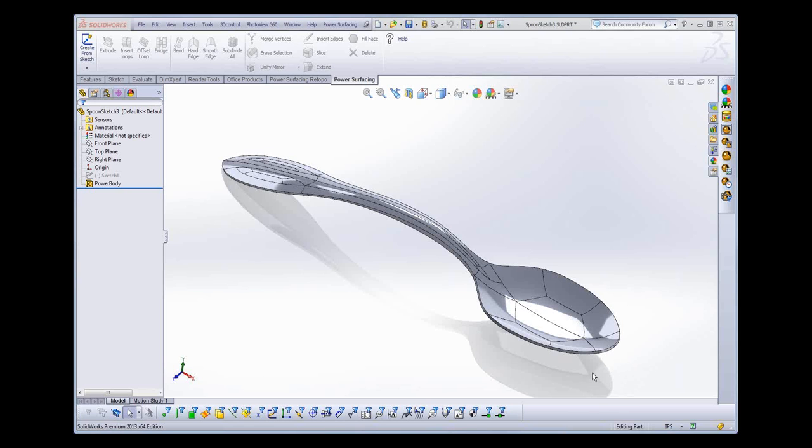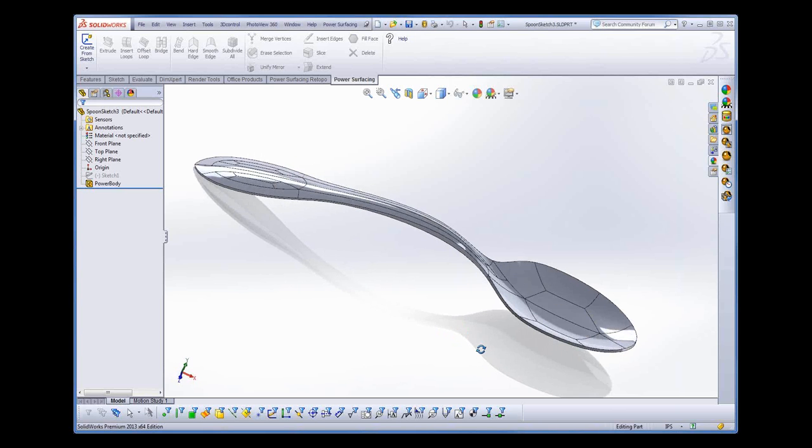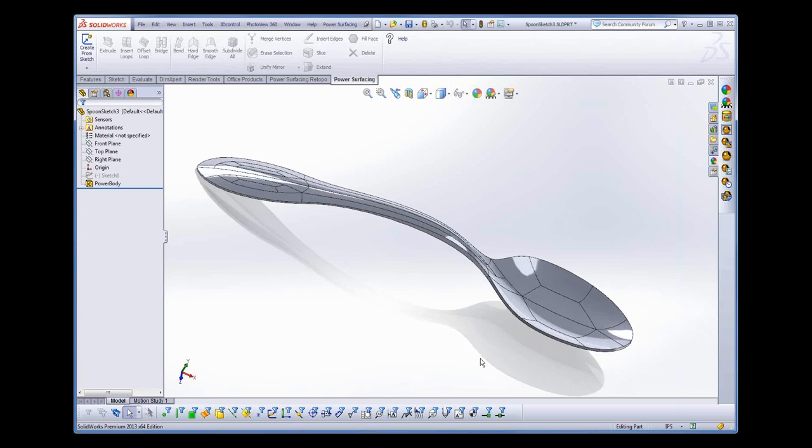One, I'm just moving the vertex, and if you think back to your splines, remember one point in the spline, the others will kind of tweak a little, or the curves in between. So that's sort of what happened there. It maintains the continuity, the curvature. It stays curvature continuous if you just pull on it. But if you crease it, you change the continuity. If you weight something, you increase the curvature around it. Whereas if you just pulled it, it still would have that same sort of radius of curvature around it. Does that make sense?